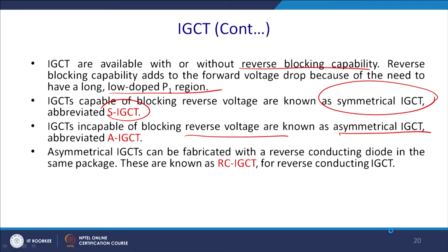Let us understand it. In the case of the voltage source inverter, you generally require the current to be bidirectional, and for this reason, in the case of an IGBT, you have to provide the anti-parallel diode. Because if you have a lagging power factor, then when the voltage is positive, the current can be negative.